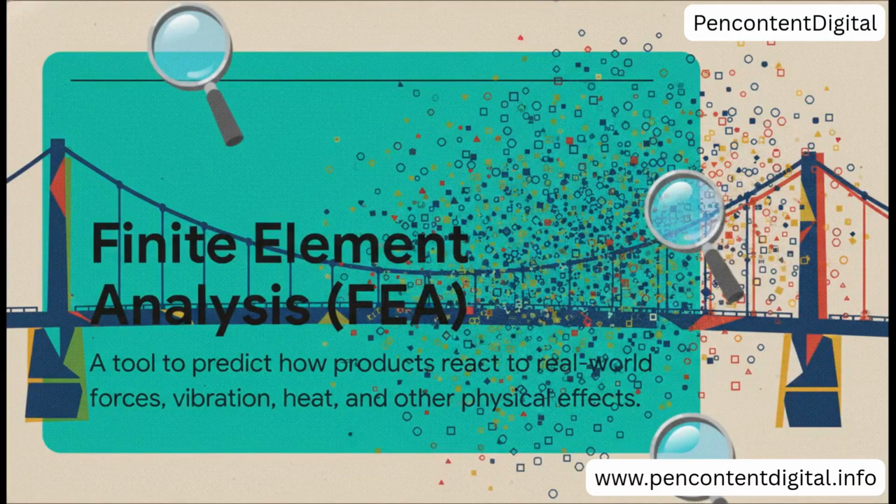The best way to think about FEA is like building with digital Legos. It takes a really complex object, like that bridge we were talking about, and it breaks it down into thousands, sometimes millions, of simple, manageable little pieces called elements. A computer can easily calculate the forces on each individual piece. Then, and this is the magic part, by adding up the behavior of all those tiny pieces, it builds this stunningly accurate picture of how the entire thing is going to behave.